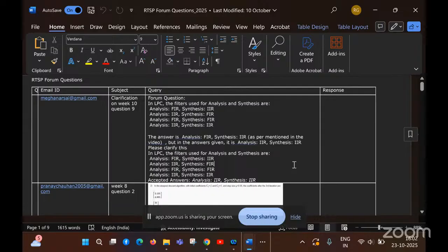Usually they use block floating point when entering filtering, and while exiting they change to normal floating point, or usually double precision, because IIR filters tend to deviate.